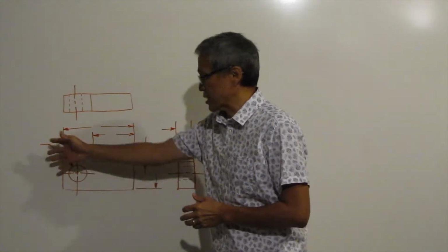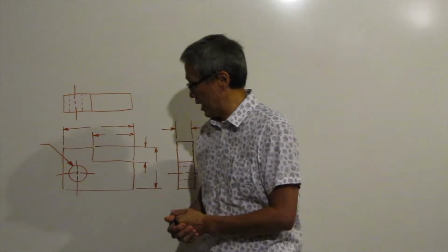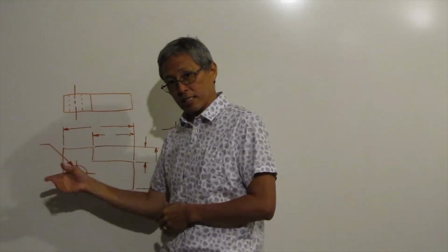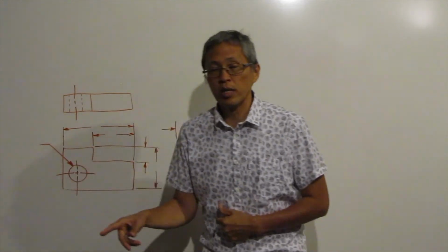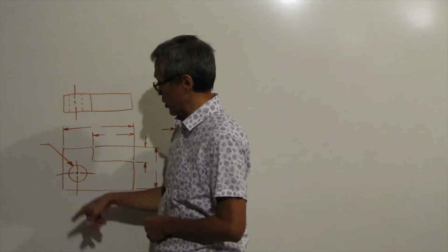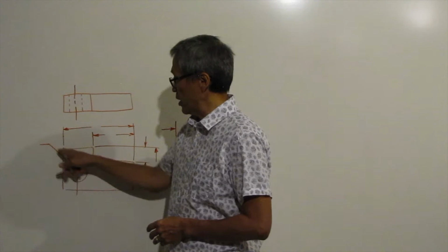And then the last one that I'm talking about on this particular drawing, this one you will never get, so I'll just tell you what it is. These guys right here, this is actually a dimension line, but you can use these lines for other things as well. This dimension line in this case that goes to the circle tells us the diameter of the circle, or the diameter of the hole. That's called a leader line.